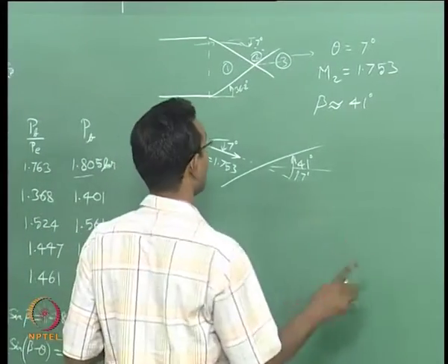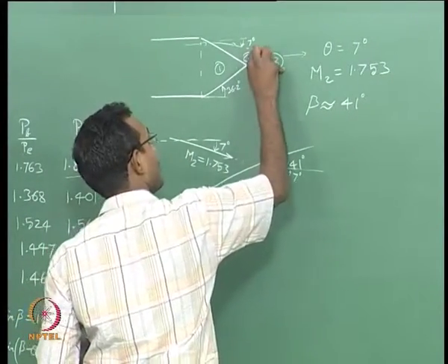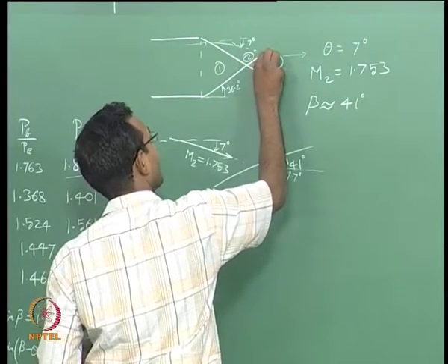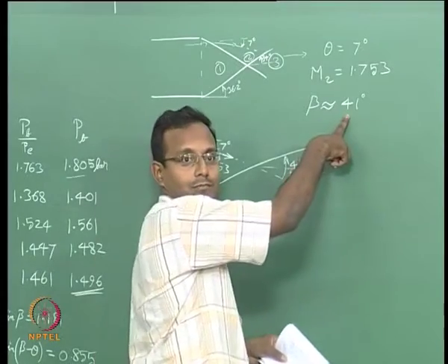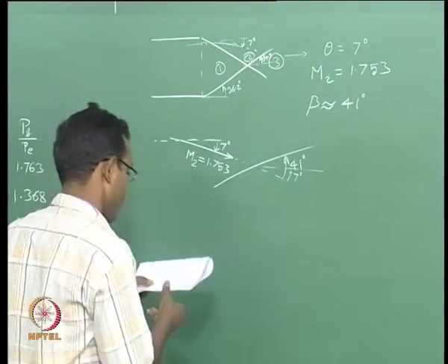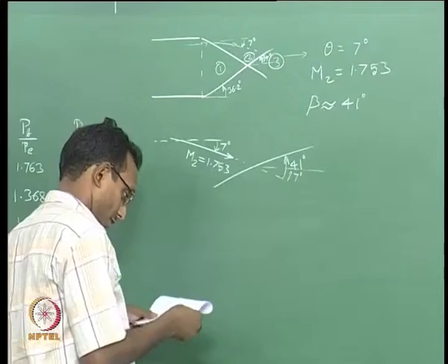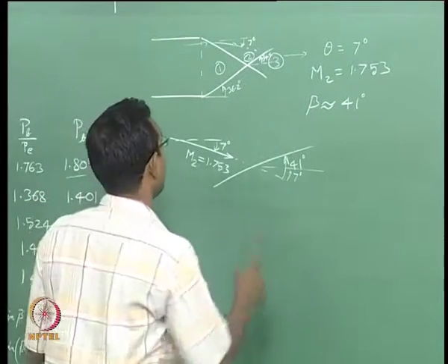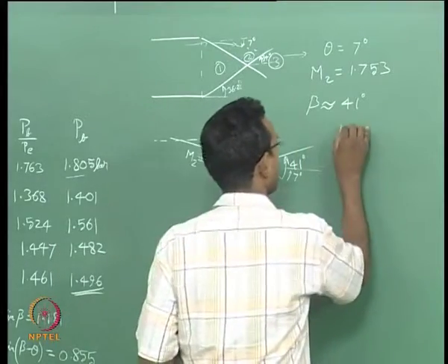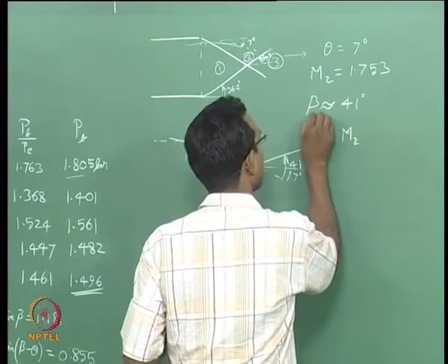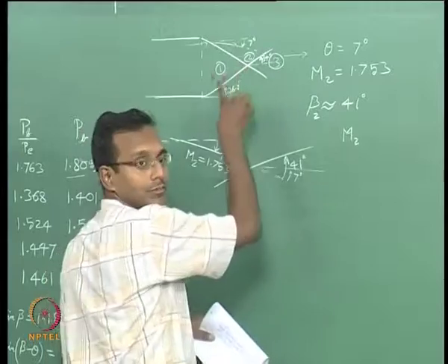Okay. So, actually if I want to draw the shock here, this angle is only 34 degrees, but what the flow sees is 41 degrees. Okay. Flow is seeing 41 degrees. So, now I just have to go and find pressure here, P3. Again simple stuff, I just have to find M2. I will put beta 2 here because this is the second shock.